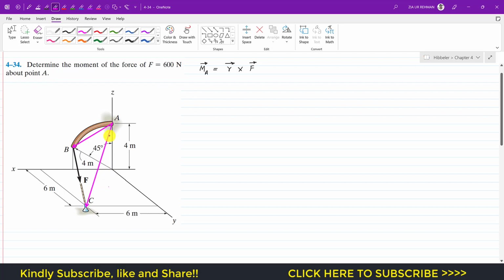So now it's up to you whether you choose AB as the moment arm, or you select this RAC as the moment arm. I will select this RAC as the moment arm. So I will write this is RAC and this is that force F. To evaluate this cross product, we need the Cartesian vector representation of this RAC and that force F. The magnitude of the force F is given.